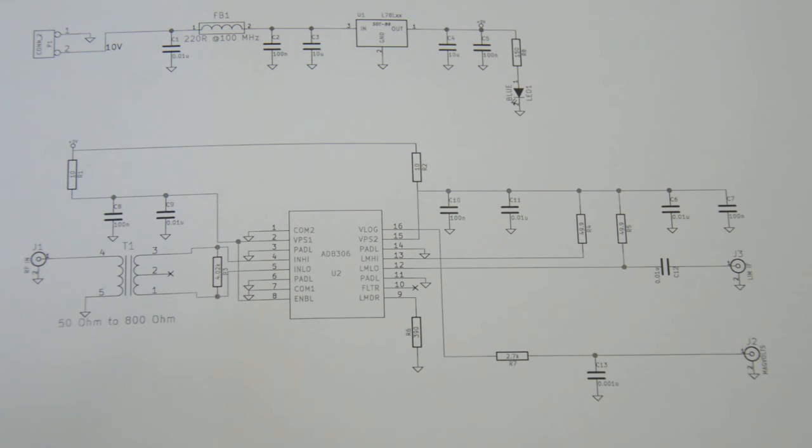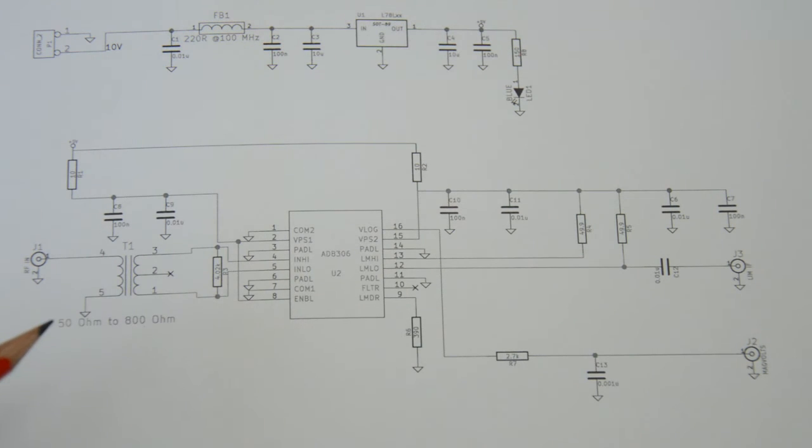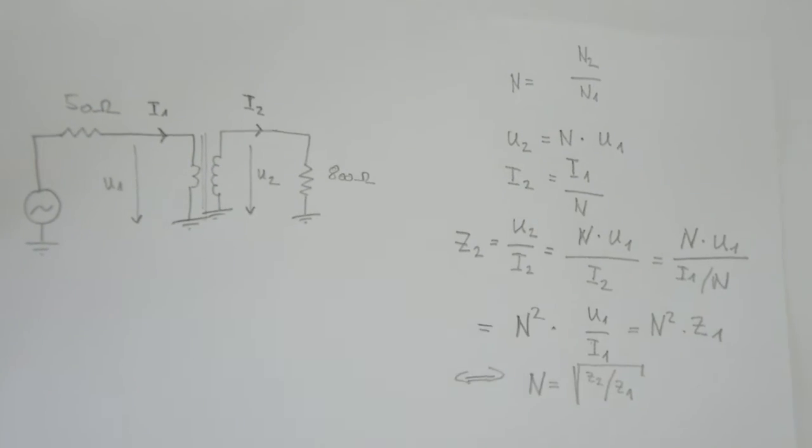And so I decided just to link in an explanation to it for now and just assume that the impedances have to be matched. Because if the impedances are not matched, there is horrible stuff going on in general, and really you want to have 50 ohms of input impedance in that part here. So I still want to explain what this transformer does here, and that's why I have this little sketch here.